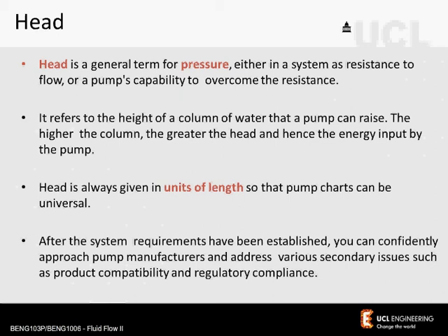and the more energy it is giving the fluid. Head is always given in units of length, so in meters, so that pump charts can be universal. So it's basically a trick for making engineers' lives easier. And once you have defined the values of the potential, kinetic and pressure head for a system, you can confidently figure out what pump power you'll require.